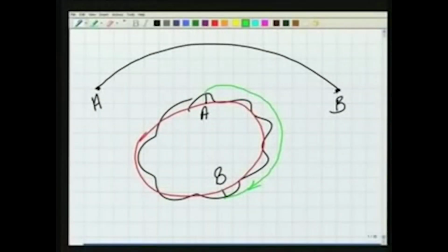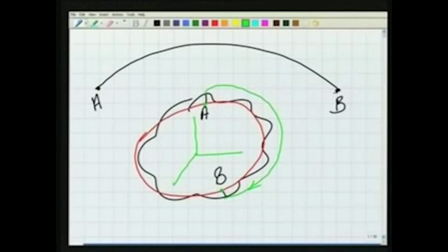So we can do this thing only if we know the coordinate of point B and coordinate of point A in one reference system. And now the one reference system for us is the ellipsoid. Now how do we define the ellipsoid? The ellipsoid will be defined by a coordinate system which has its origin somewhere in the center of the earth. So we will talk about that in detail in our other lectures. So for this reason, because we need coordinates of any part of the world in one reference system, we need to define this kind of reference system.